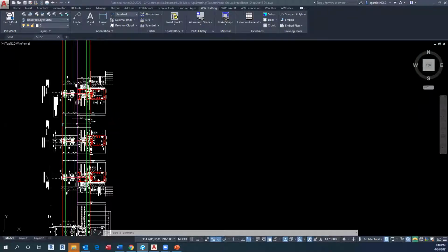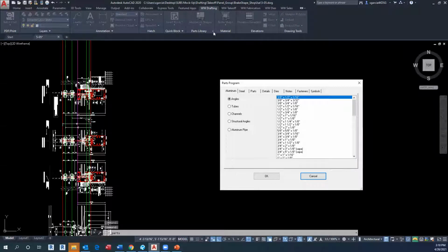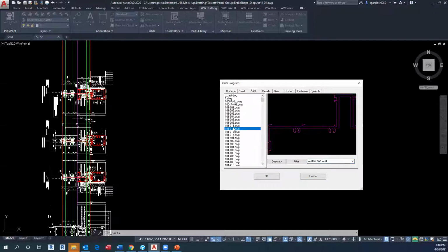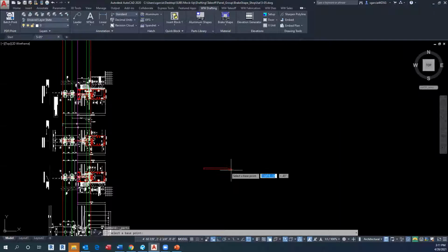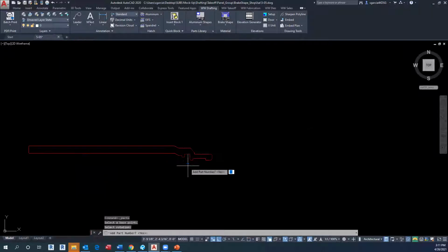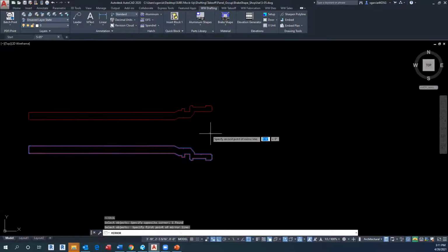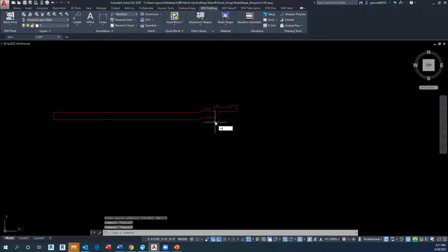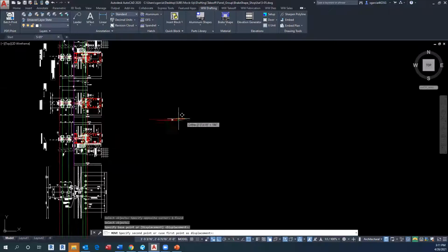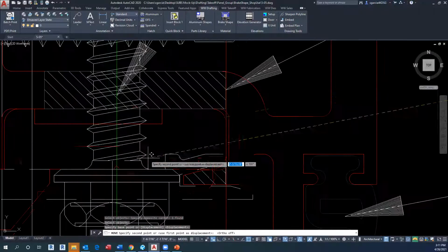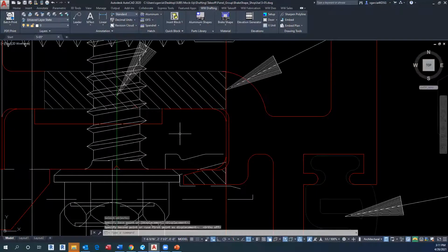So if I go to AutoCAD, I can go to drafting, go to the parts library, and click here on the part below. Let's first import the die. If I click on parts die and type W75 5696, I have the part. What I'm going to do is just paste it here, mirror, and then move it just to verify that I'm using the right part in my details and it's matching.